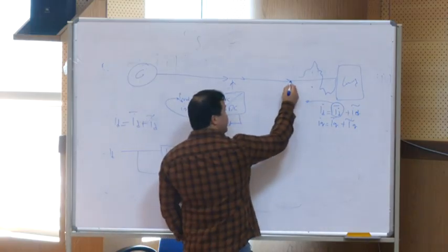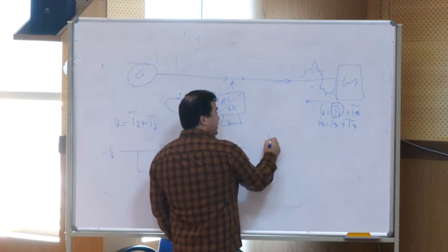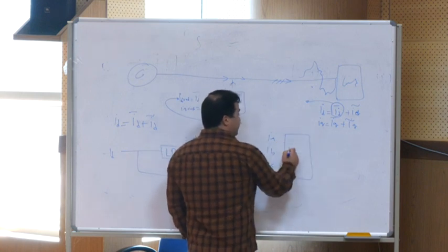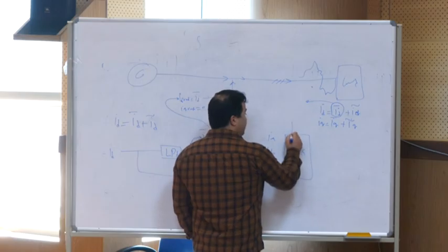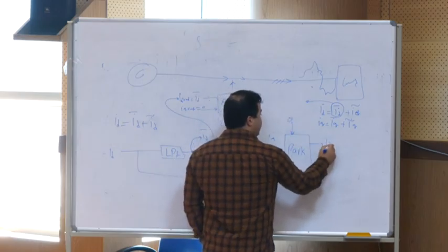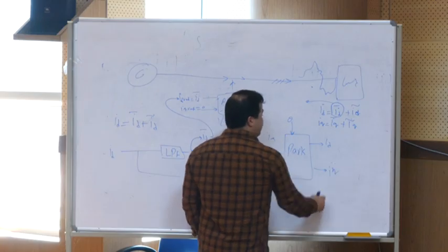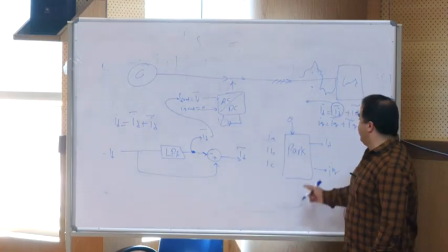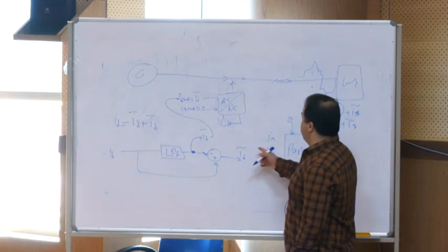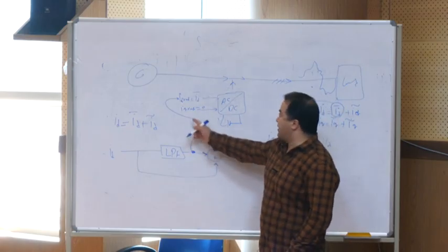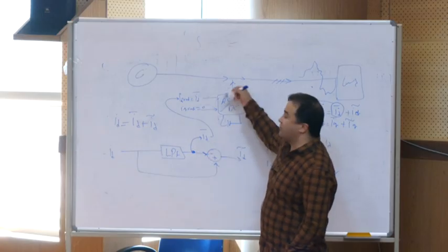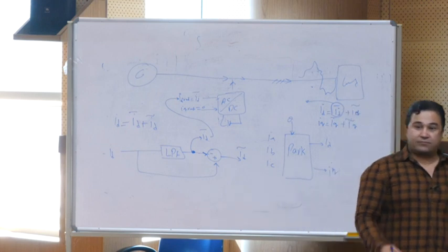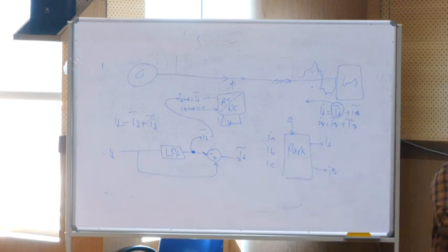So how is it possible? For the simulation, you have the three-phase system, IA, IB, IC. So we give it to Park with the theta of the grid. We get ID and IQ. That's much easier. Okay, then we split the ID, get the DC value from after the filter and put it here as a reference. Then the converter injects just active power in fundamental frequency. Am I right?